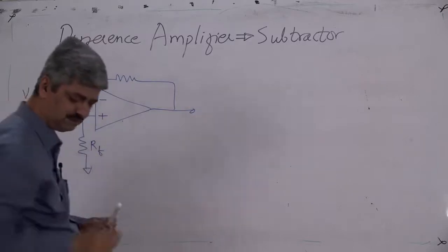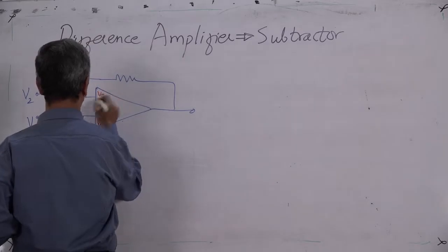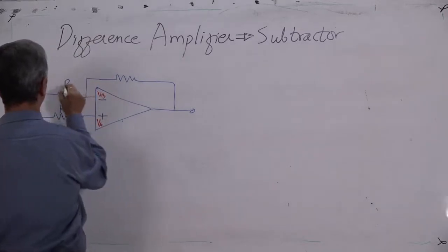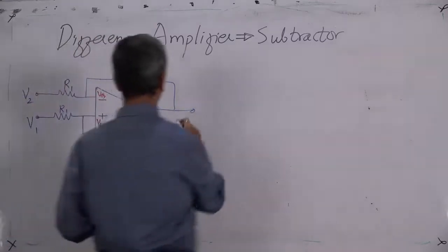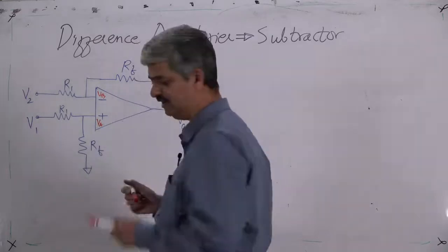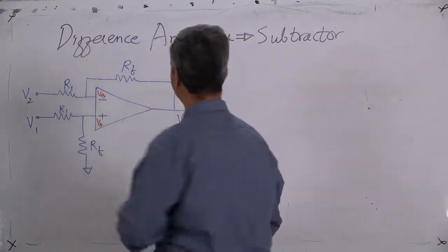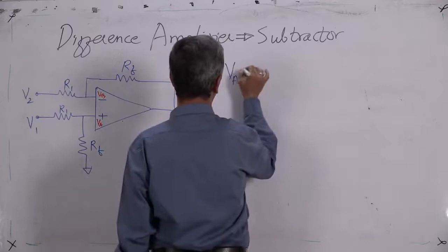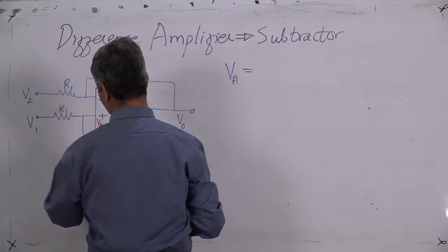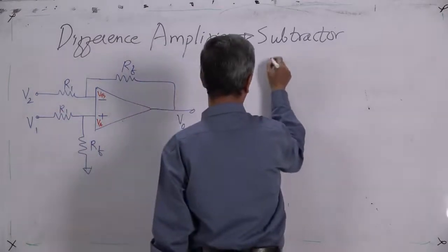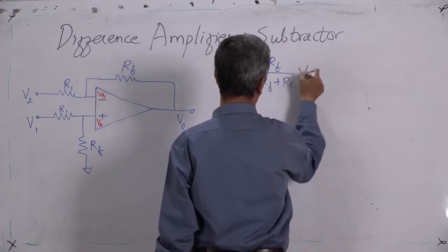This you always need to write, that is our crux, that is VA, VB, and this is VO. Again, everything is the same. What is V? Disconnect the op-amp terminals, that need not be told. What is VA? VA is equal to RF upon RF plus R1 into V1.